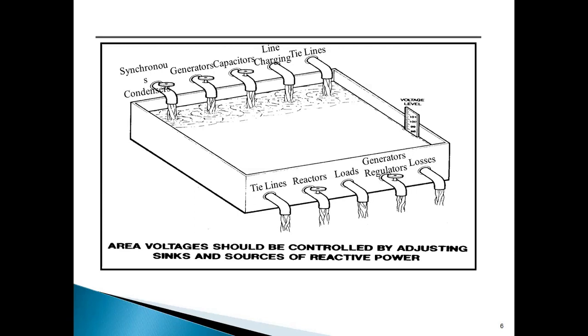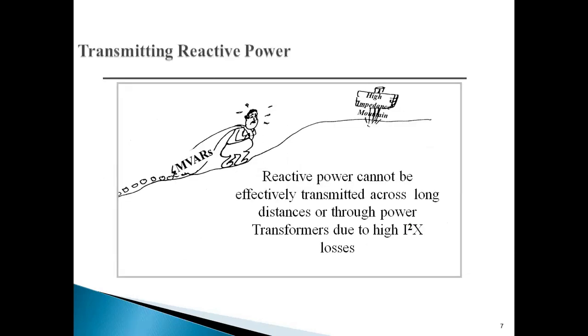Okay, so with this I will try to end this slide. I hope you are all able to remember the concept of generation and absorption of reactive power. And though we are enjoying the benefit of reactive power, we should know that we are always interested to locate or connect the capacitor bank or the static var compensator at the load end, because voltage stability is load driven,